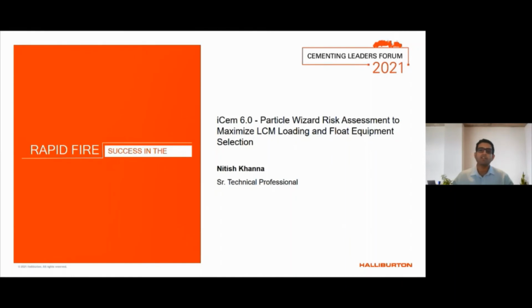However, introducing LCM in fluids does pose certain risks in terms of plugging any restrictions in the wellbore, like valves or ports in casing equipment. Therefore, it is extremely important that we use a quantitative approach to minimize the risk and maximize the probability of eliminating or reducing losses.